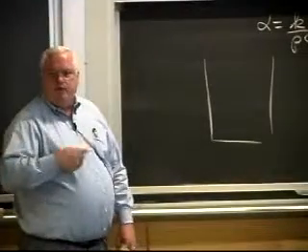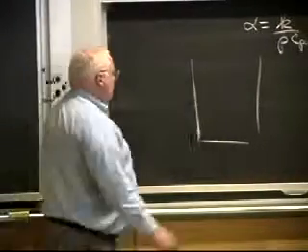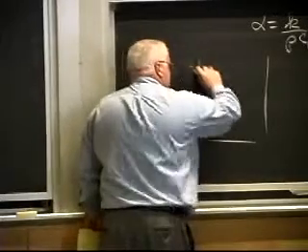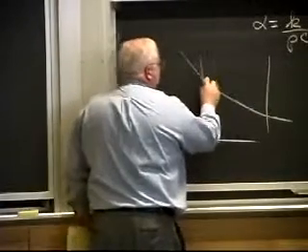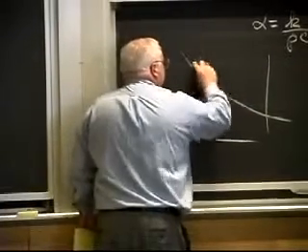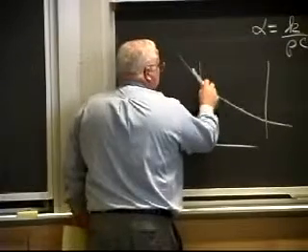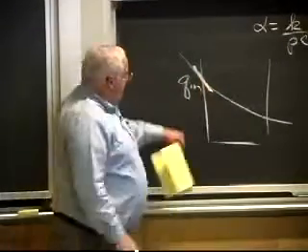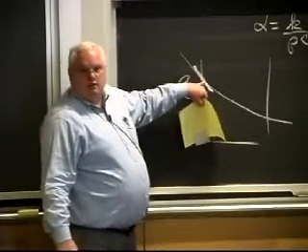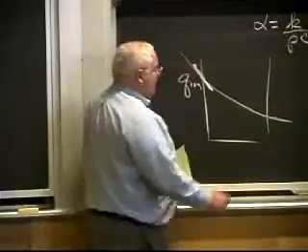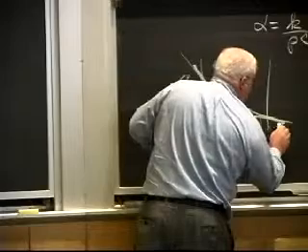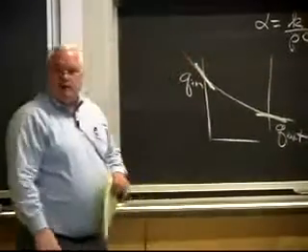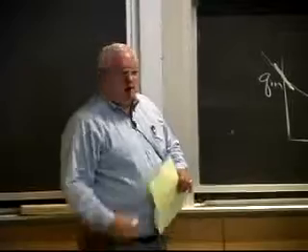If I have heat flowing into some solid body, I just take a little volume element, and if I have some temperature profile across this volume element, Fourier's first law says that the rate of heat flux Q in to this little volume element is equal to the gradient times the thermal conductivity. The heat out is also the gradient times the thermal conductivity, minus K dT/dx.